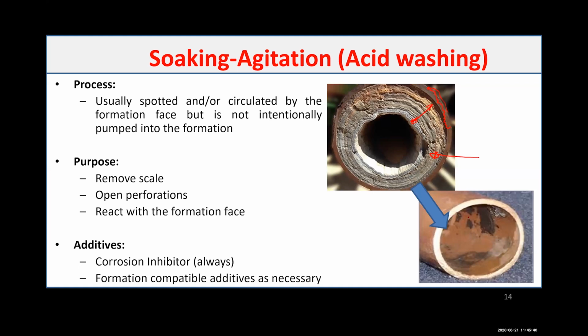It can also help to remove any scale from the perforation. And sometimes some of the scale will be in the formation face, so we can pump the acid to this formation face. Again, when we are doing acid washing, our intention is not to pump it inside the formation. As a maximum, the maximum location is just the formation face.